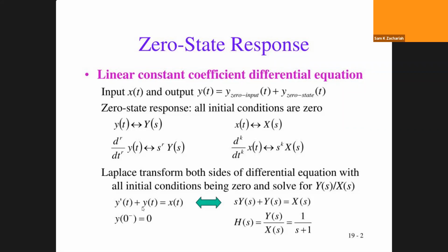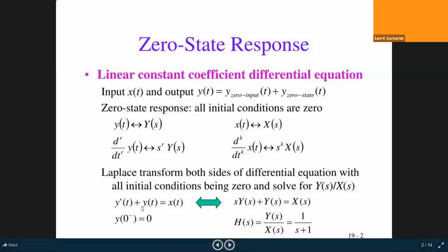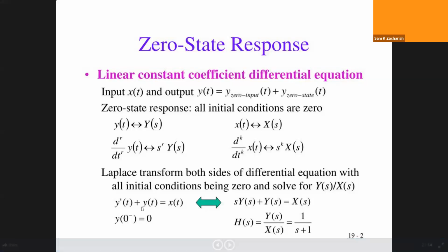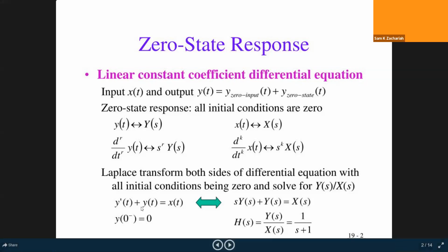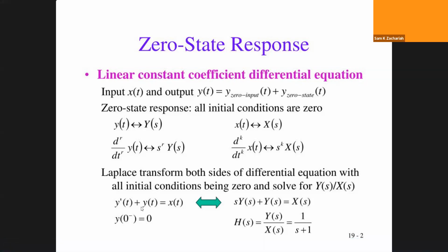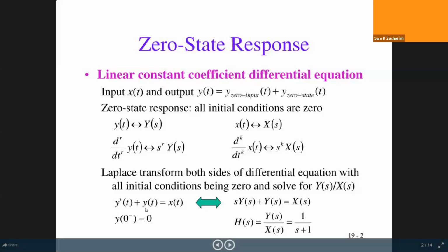And here C is equal to 1 farad. So you get output voltage V is equal to Q, the charge across the 1 farad capacitor. Now the current passing through the capacitor is dq by dt, that is the derivative of y(t), y dash t. That current is passing through a 1 ohm resistor, which will produce a voltage drop of y dash t across the resistor. So in the RC series, the applied voltage is equal to the voltage across the capacitor plus the voltage across the resistor.